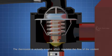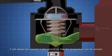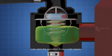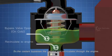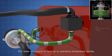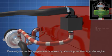The thermostat is actually a valve which regulates the flow of the coolant. It will always be covered in the coolant, so that the temperature can be sensed. Let's start the operation from a cold engine. When the engine is cold, the bypass valve stays open. So, the coolant bypasses the radiator and recirculates through the engine. This helps the engine to heat up to operating temperature quickly. Eventually, the coolant temperature increases by absorbing the heat from the engine.